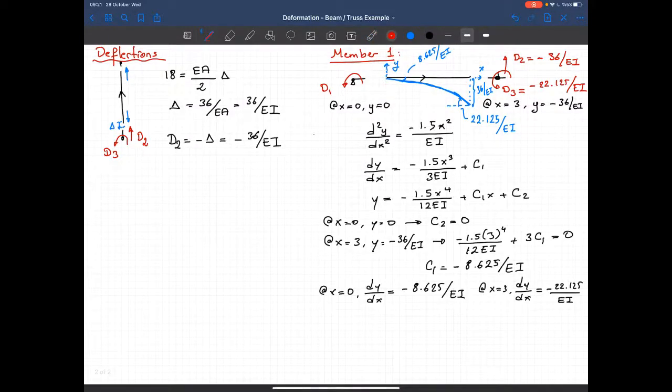I will be using this space for it. Now I'll use the same approach for the second member. That's the start node of that member. This is my second member. That's the end node. That's the direction that I choose. So this will give me the x direction as follows, and this is the y direction. Now let's show the degrees of freedom. I got D2 and D3.